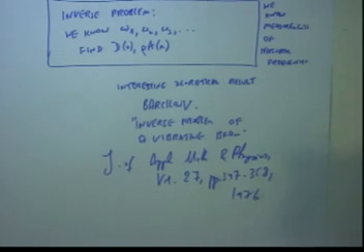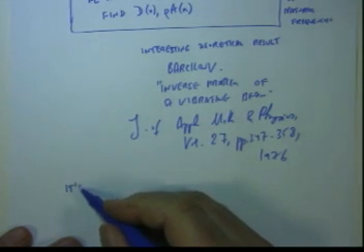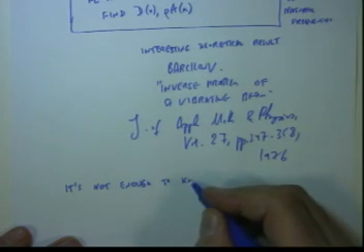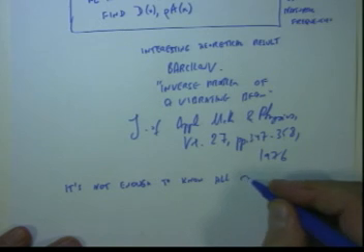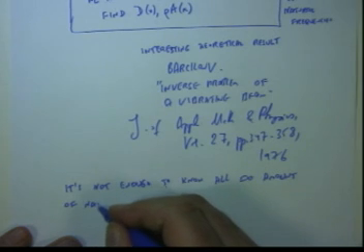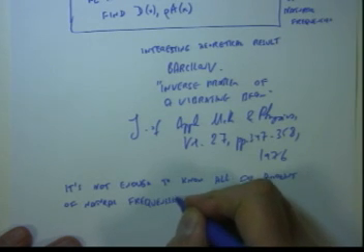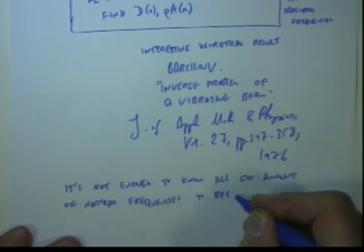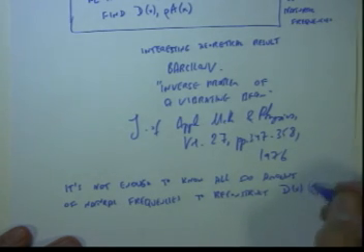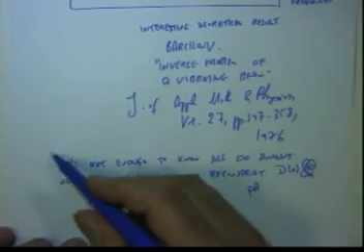So this interesting result is as follows. You may want to write down this result. It is not enough to know all infinite amount of natural frequencies to reconstruct D(x) and rho A. Not enough.